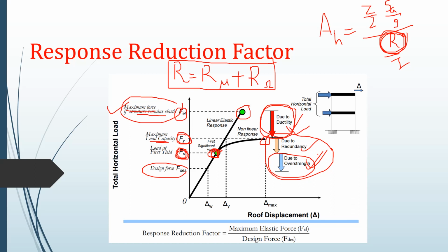We may have strength contribution of non-structural elements. For example, if we are designing a moment resisting frame, there will be the presence of infill masonry walls. We do not consider the contribution of those infill masonry walls, and we consider them non-structural components in our building. But our considering them non-structural does not mean that those infill masonry walls will not contribute to the stiffness of our structure.